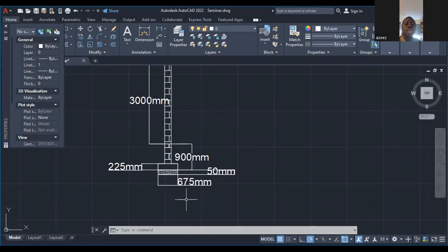If you want to put steel, we are going to use RCC, reinforced concrete, because you will reinforce it with iron. But the other one is just mass concrete, where the mix ratio may not be as serious as RCC. They are both different forms of concrete, but one is more expensive, more cement concentrated than the other.